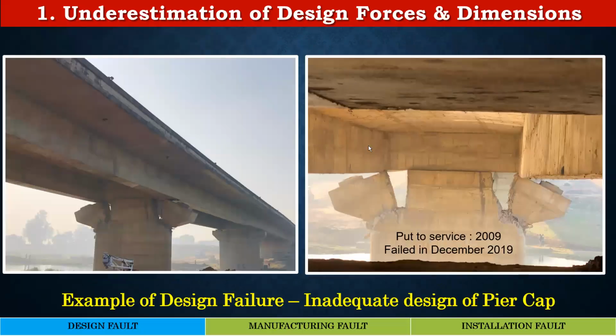Third example is again the Karamnasha bridge, which I mentioned failed in December 2019. It is not the failure of the bearing actually, but the failure of the support to the bearing. And you can see here that there is hardly any reinforcement in the bracket, which has caused the failure.